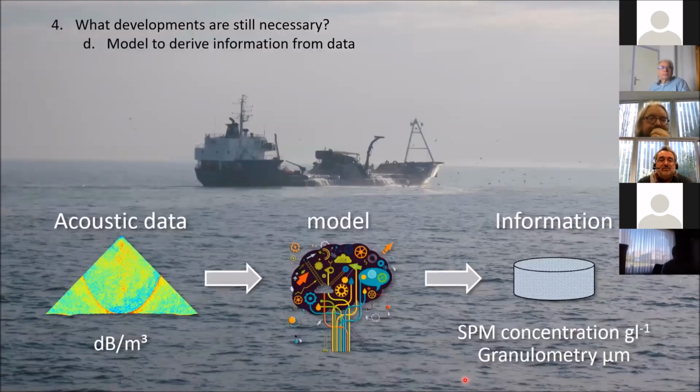Okay. The last point I want to evoke with you is the necessity to establish models which will allow us to derive the concentration of suspended particles, assuming an average particle size. To transform, to invert the acoustic data to information, to translate this decibel value into SPM concentration, in grams per liter.